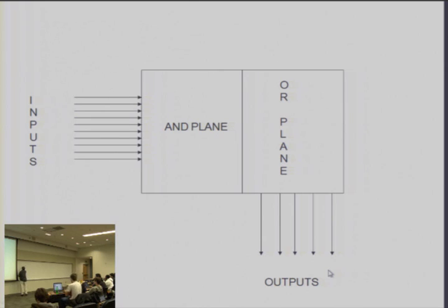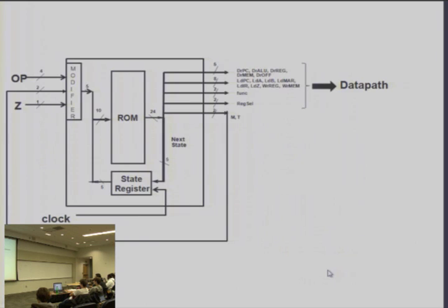and an example of such a logic function would be, let's say, drive PC is one logic output that I want to get out of this control unit. Now, if I wanted to implement drive PC as a logic function, I can say what are all the states in which I need drive PC.